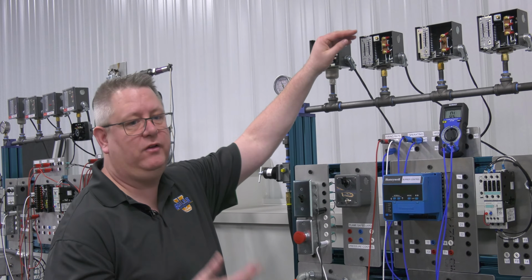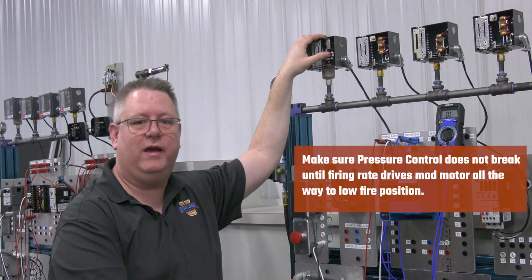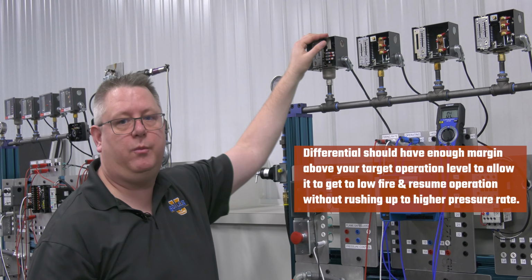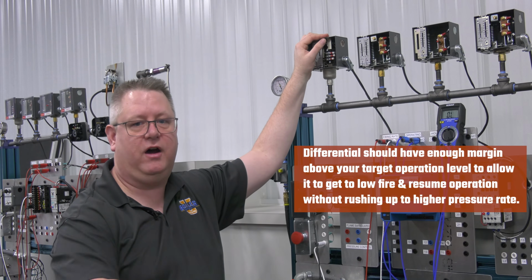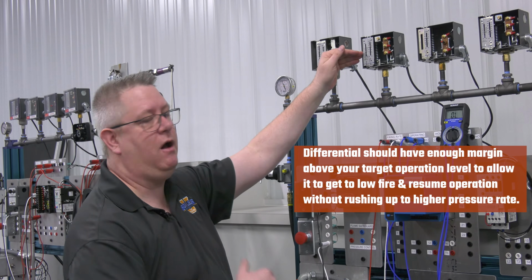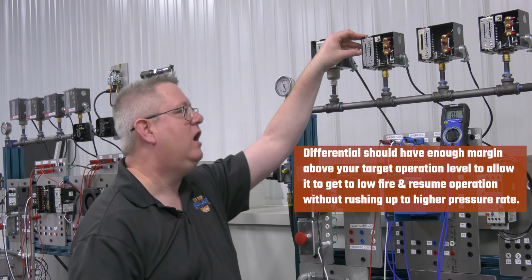So I always want to make sure that my pressure control does not break until my firing rate has had a chance to drive the mod motor all the way to the low fire position. And I also generally don't want my differential so large that when the boiler comes back on, it goes roaring up to high fire. I want it to have enough margin above where I really want to actually operate at to allow it to get to low fire and to allow it to resume operation without having to rush up to a higher pressure rating.